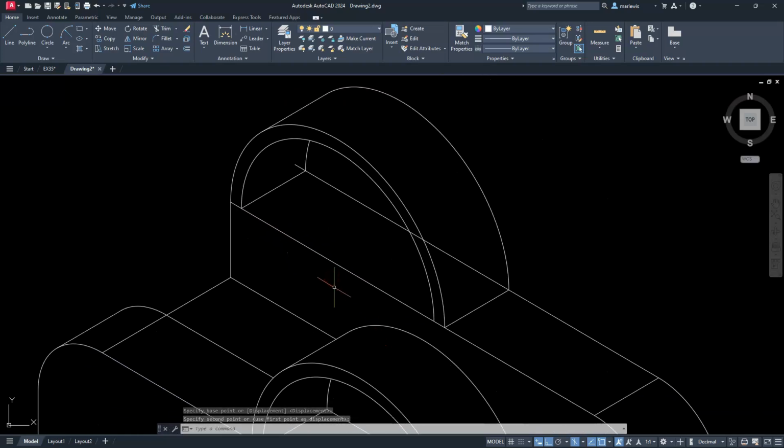And I'm just trying to look around this and see if I see anything else that's out of place. Everything else looks good. Let's go to the trim command and start trimming off some of this stuff, right? So we don't need to see that. We can leave this on here. Technically it's not there, but that's kind of up to you. Let's go ahead and get rid of it. And then we're going to trim in between this line and that one.